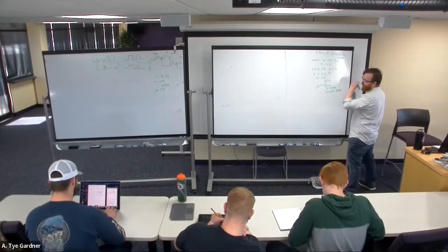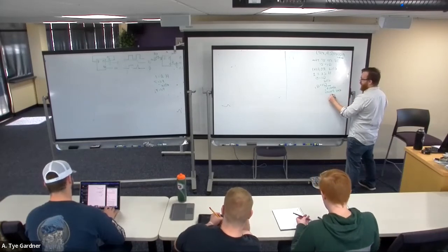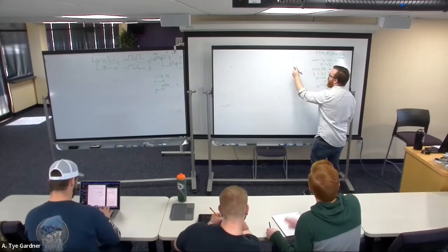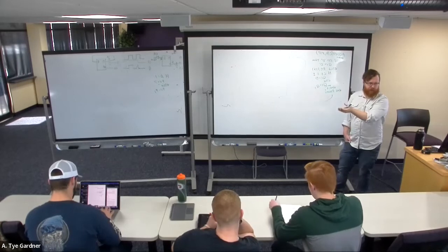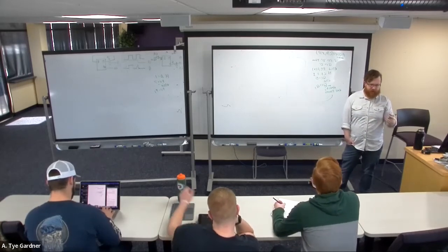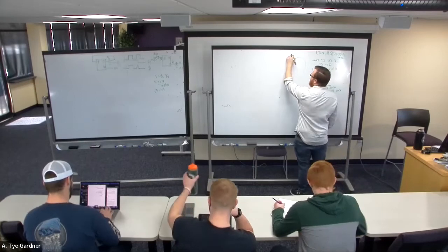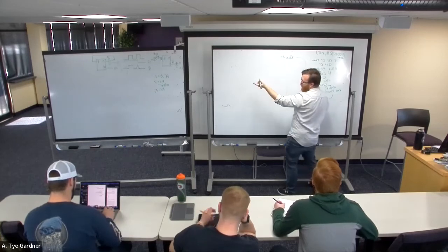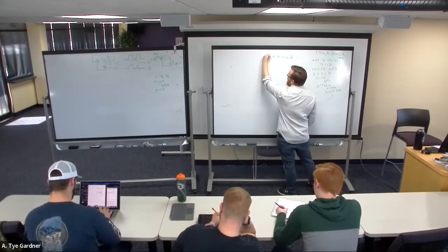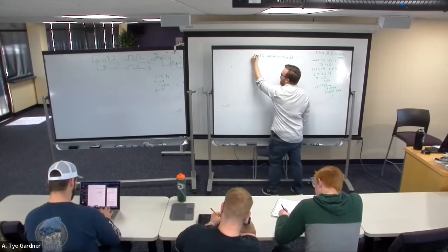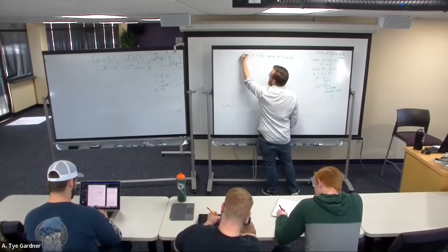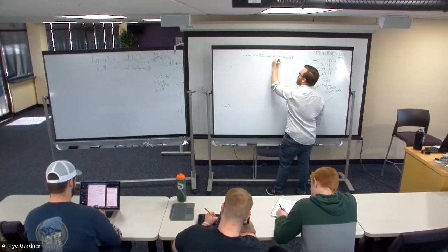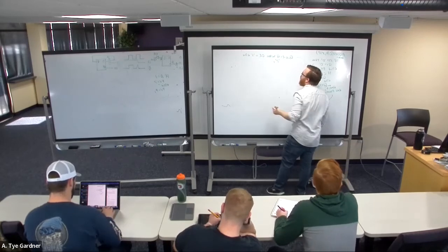buffer, and that is simply as easy as going with a when else statement, it turns out. In fact, I'm going to bring it up here so it's easier for those in the back to see. So this is after the end process, but before the end of the architecture, right? We're still inside the architecture at this point. Now what I want is to say that Q output is going to be, well, Q when OE equals 1, else high impedance.